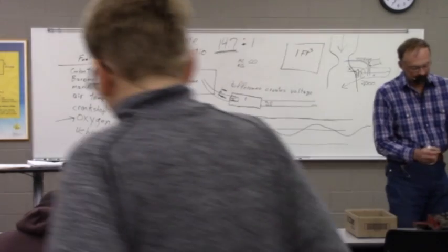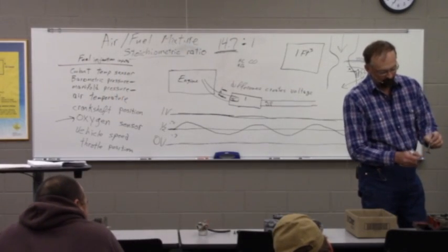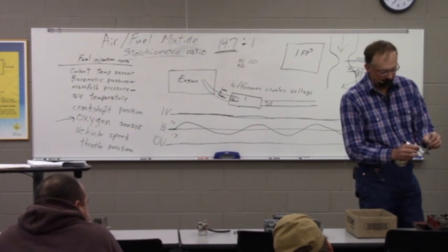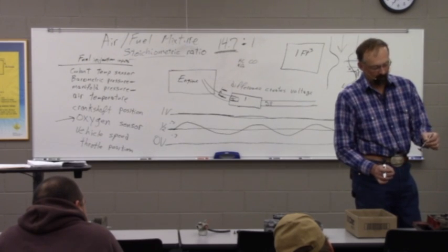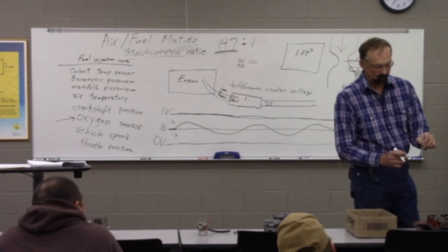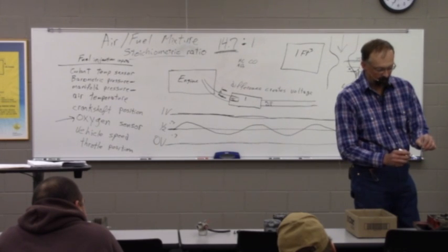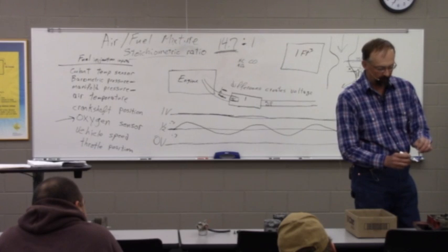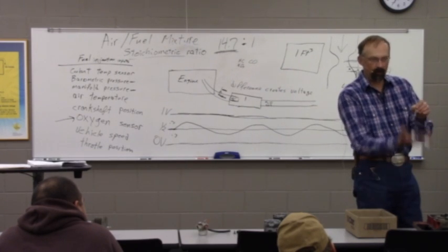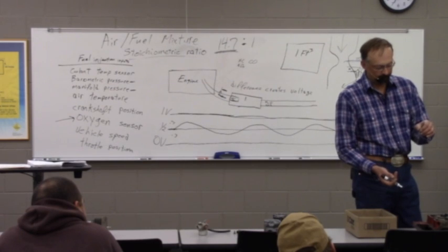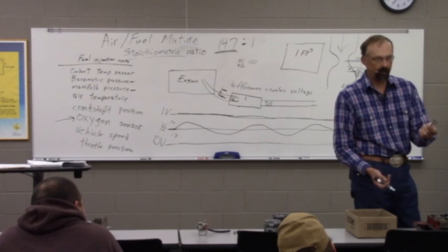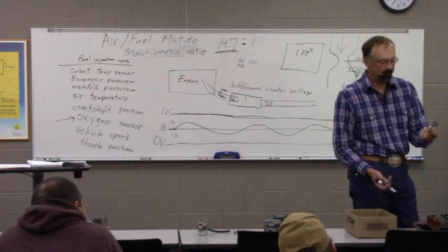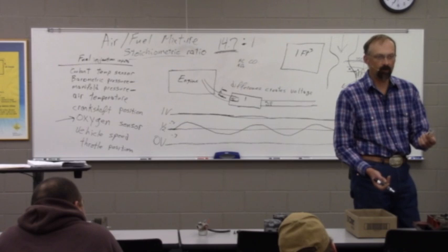When this valve is coming shut, and it's doing so pretty rapidly, this metal face slamming against the seat was an issue, and they found that with some lead in the gasoline, there'd be just trace amounts of it on this surface, but it cushioned that valve slamming shut. With the advances in metallurgy, the metal these valves are made out of is incredibly better than it was 50 years ago, and honestly, that cushioning effect's no longer necessary.